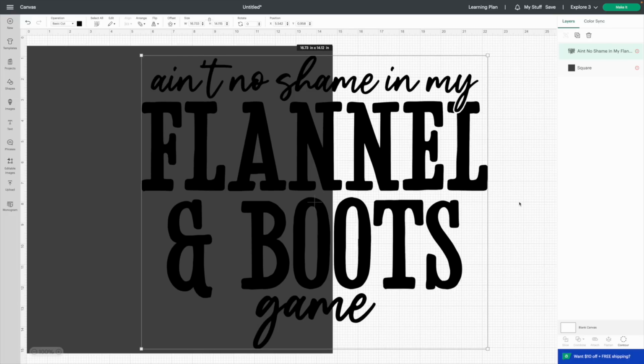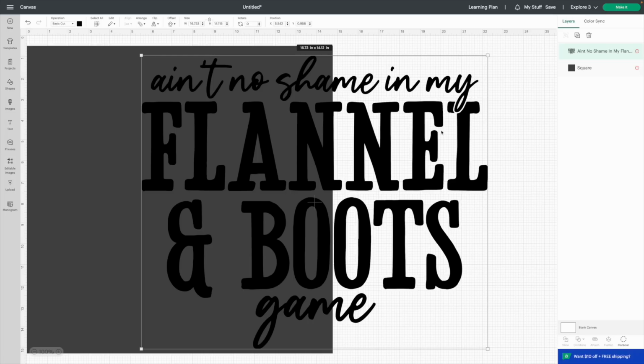So in order to slice this, the only way that slice will work, I see this question all of the time, is there can only be two pieces. So say for example, this design was 3 pieces and I selected it and then the square, it would not work. This has to be welded down to 1 piece, so you should have 2 pieces here. There should not be like 5. It should be 2 little pieces here. So what you're gonna do is select both.